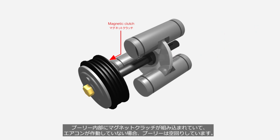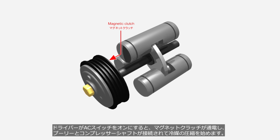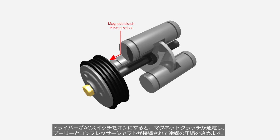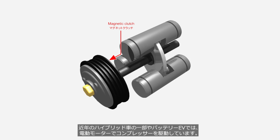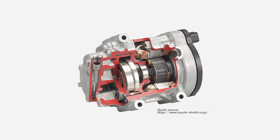A magnetic clutch is installed in the pulley. When the air conditioner is off, the pulley rotates idly. When the driver turns on the AC switch, electricity is supplied to the magnetic clutch, and the pulley and the compressor shaft are connected. Then the compressor starts to compress the refrigerant. In recent years, some hybrid vehicles and battery electric vehicles use an electric motor to drive the compressor.